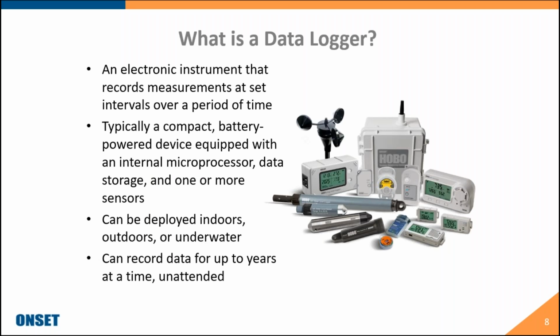All right, so what is a data logger? A data logger is an electronic instrument that records measurements at set intervals over a period of time. Typically, these are compact battery-powered devices equipped with an internal microprocessor, data storage, and one or more sensors. Data loggers, and specifically the Hobo data loggers, can be deployed in indoor, outdoor, or underwater environments, and these can record data for up to years at a time, typically unattended.